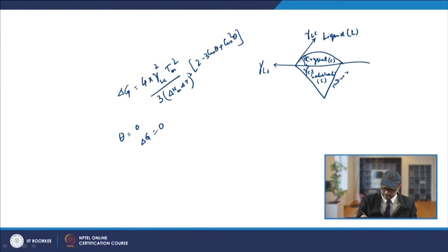In these cases the nucleation occurs by the arrangement of atoms from the liquid metal upon the substrate grains without altering their crystallographic orientations, and such a process is known as epitaxial growth.